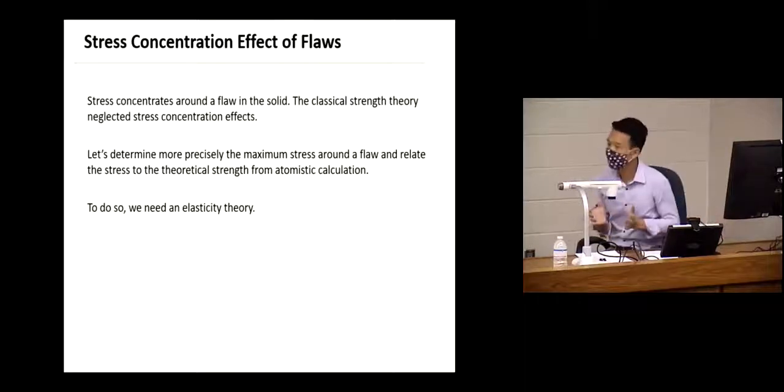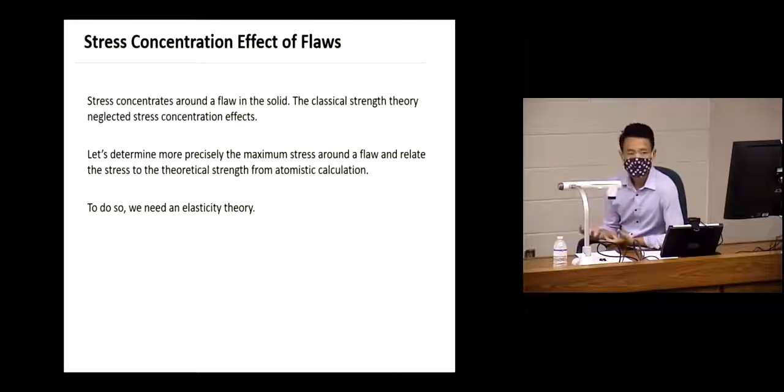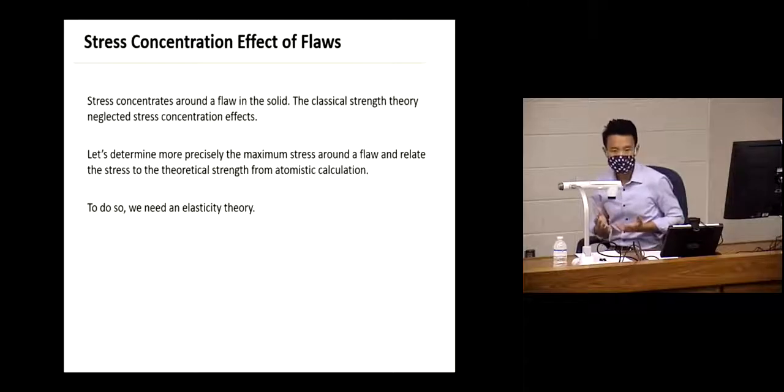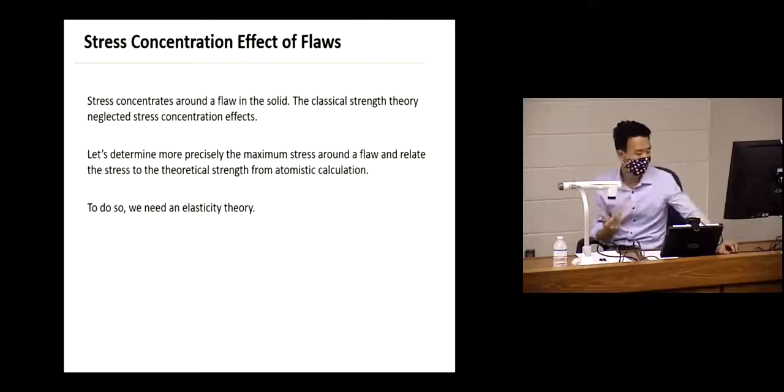We want to assume there's a flaw inside the body, right? There's a hole inside a piece of solid. And we want to use the theory of elasticity to calculate a more precise value of the stress around the flaw when we apply a certain amount of macroscopic stress, right? And see if that stress will help us get closer to that theoretical calculation.